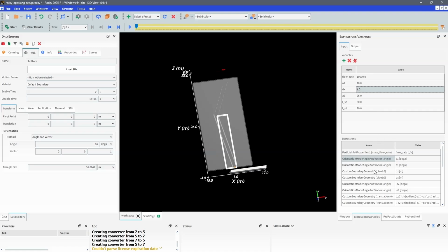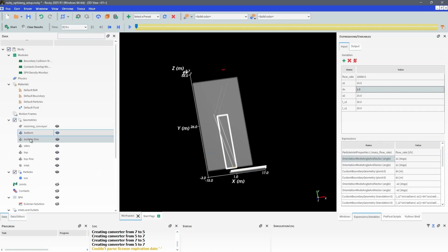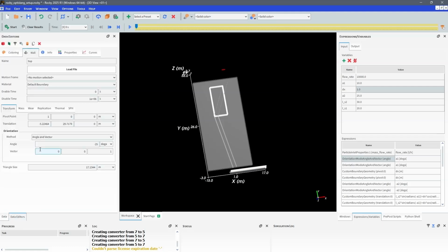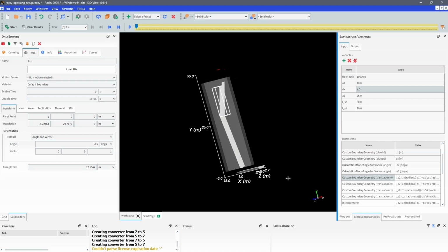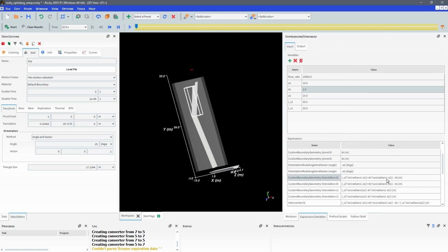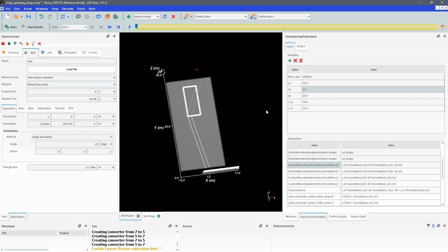Okay, so I applied it to various things, such as the positioning. Let's say we look at the top. I looked at the positioning. In this regard, I typed in an equation. Once I pressed enter, it will add it to the expressions, so you can see the expressions that were used, or the equations. I can then further manipulate these equations if necessary. I then applied it to various things in the project to drive information, or where I want to extract information, and as well driving the actual geometric positions and angles.